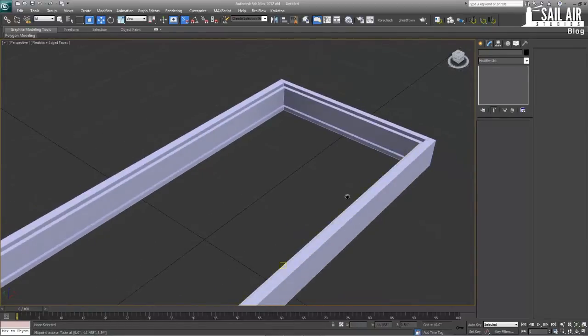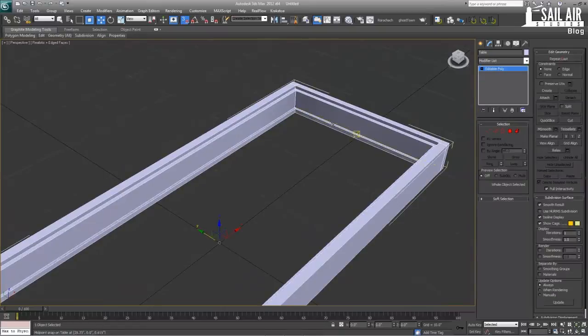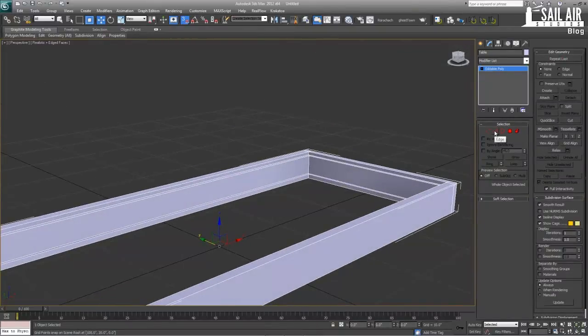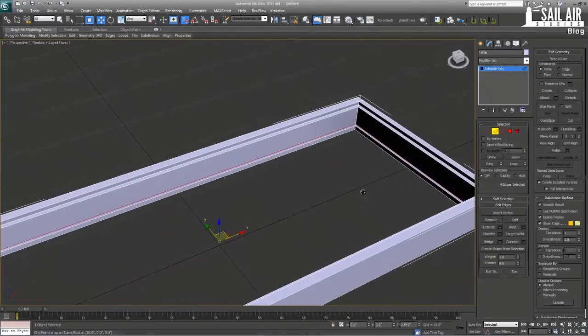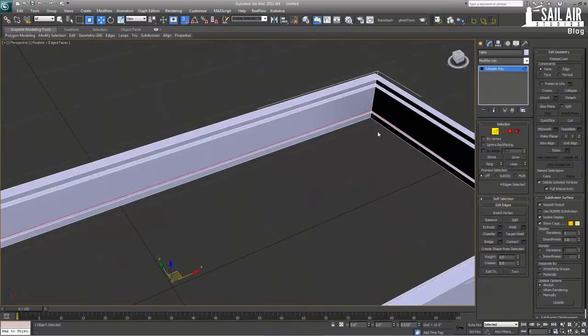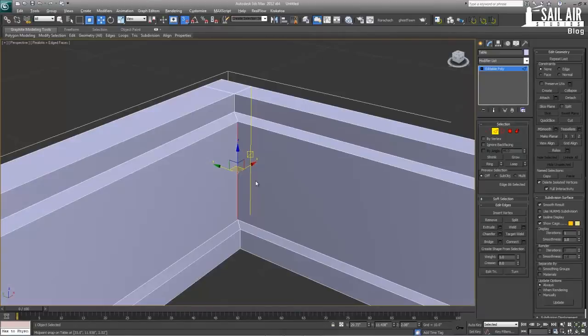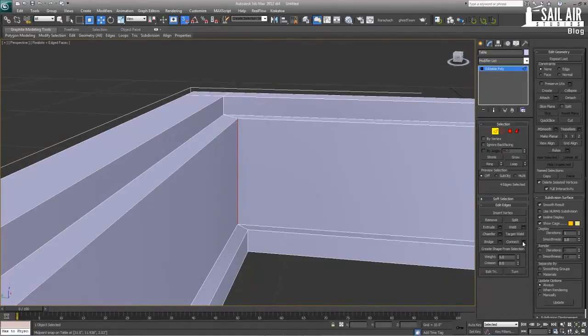Next, under this area, we're going to make the inset for where the LEDs will go in. So select this edge right here, ring, connect, 1, 0, 0, 0, that's good. Chamfer it, clicking that button. Chamfer it, I would say by 1, because that allows enough room to get it.